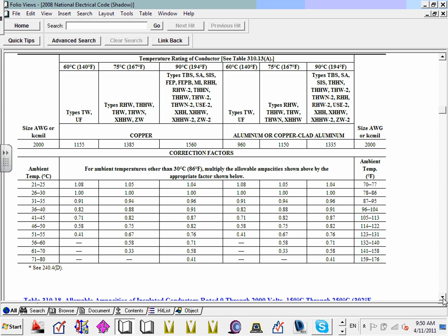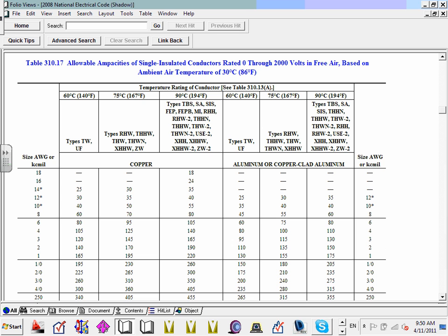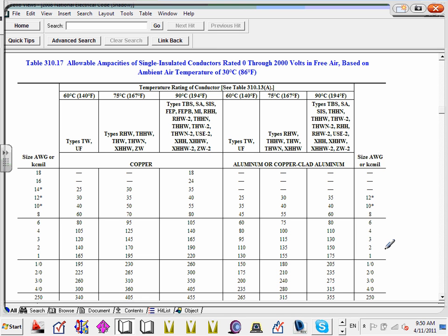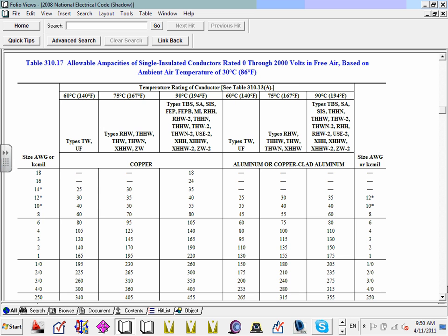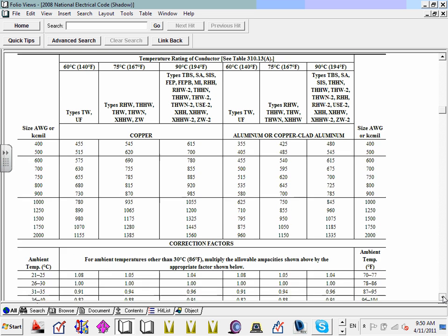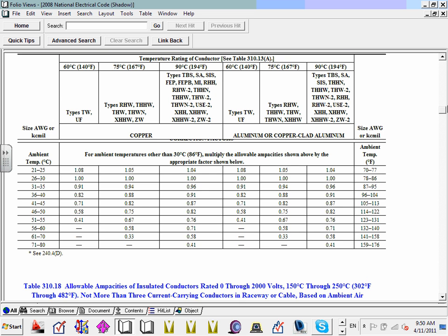So suppose, Brad, the cable tray was in an ambient temperature of 150 Fahrenheit. Then you size a conductor under the 90-degree column, derate it based on the 90-degree column, and cut it based on whatever application. 150 will put me right in here. Okay, let me see here all the way. This is cable tray.